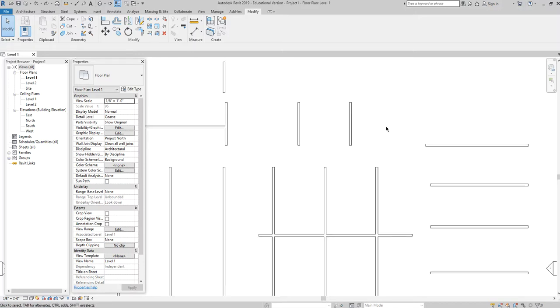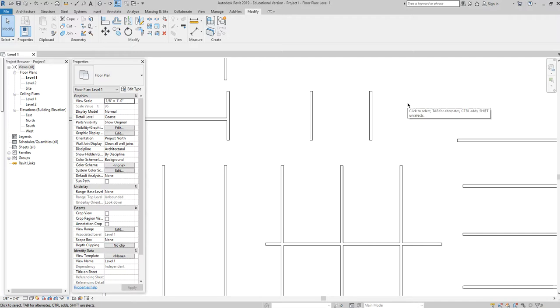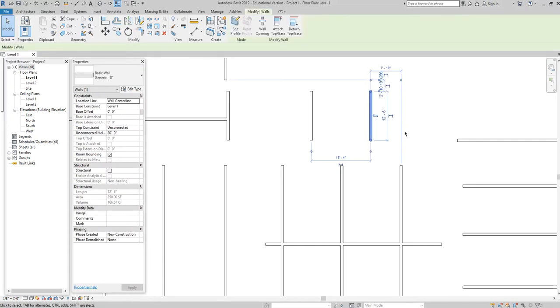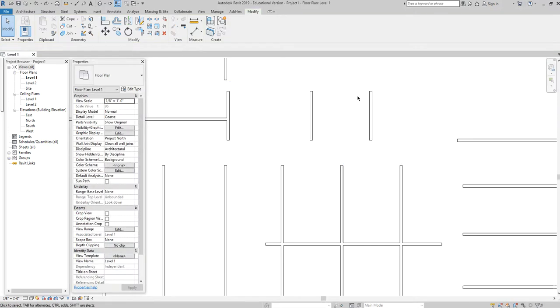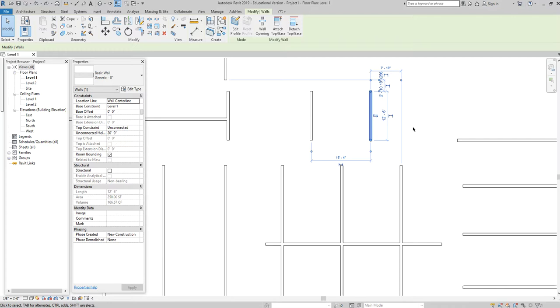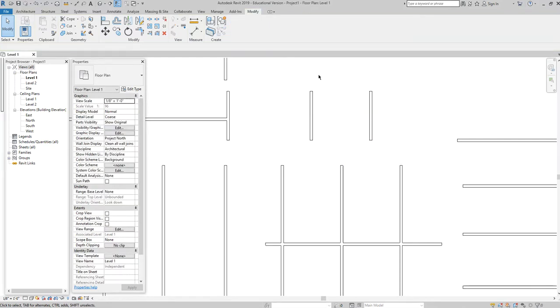I think generally speaking in Revit, the way that you'll see me functioning with move, copy, rotate, any of those type of commands, is you'll see me selecting an object first and then I'll execute a command, all right? It just doesn't feel quite as natural to come up here and click on copy, right? And then to come down here and click on one or two things and then have it function the way I want to, right? And I say that because in other drafting programs, once you select something, it's very common to use like a hard return to kind of set the command.